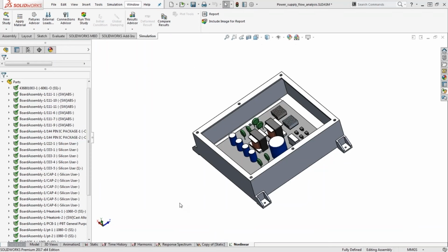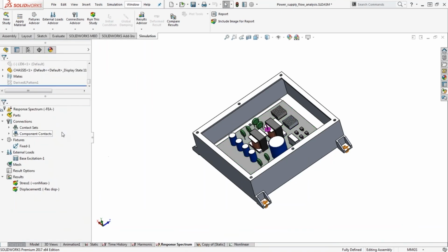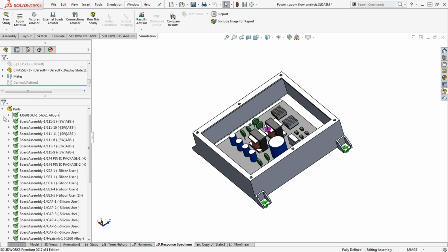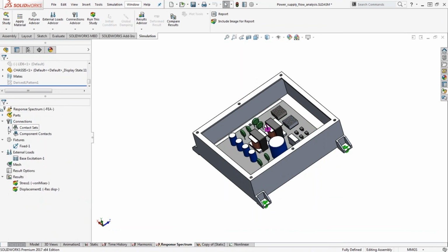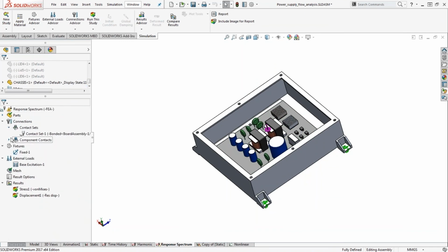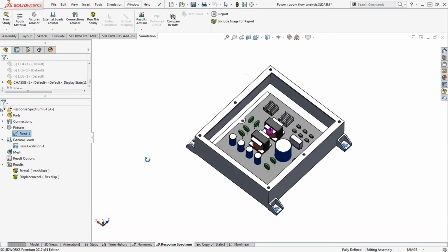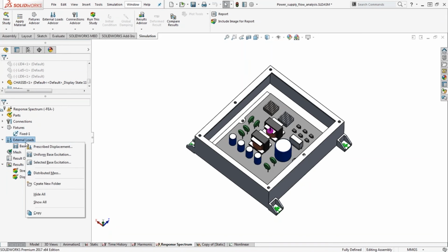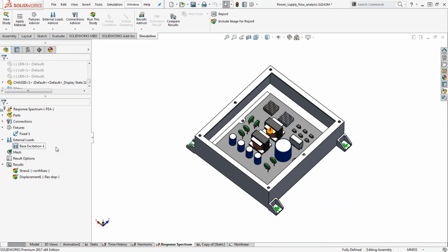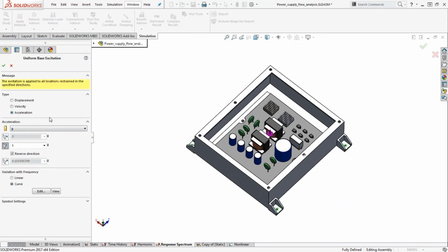The first one that I'd want to talk about is a response spectrum analysis, where, again, it allows you to define this virtual test based off this shock response spectrum data where, again, we're simulating some sort of seismic behavior, right? So we can download this information here, where I found a curve from the U.S. Geological Survey website. They give you what those load inputs are, or maybe you're working with some sort of military standard where they're giving you some sort of mil-spec standard where they're telling you what that seismic behavior, what that load input is going to look like.